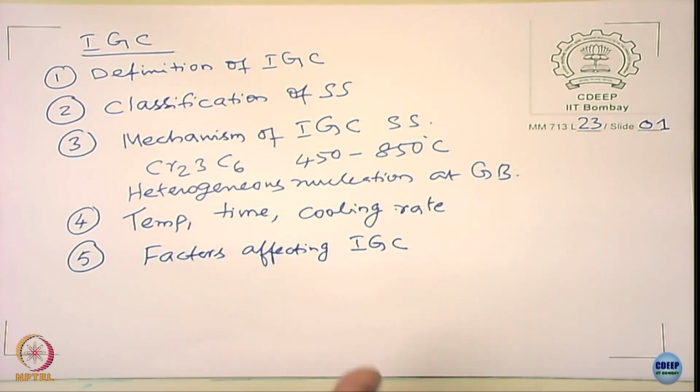You need to reduce carbon content. There is no way you can simply increase chromium content, let the carbon content remain the same, and avoid the sensitization process, okay. We discussed that in detail. In addition to carbon content, there are other alloying elements that can marginally influence this sensitization process. Some of them are beneficial, some of them are detrimental, okay.